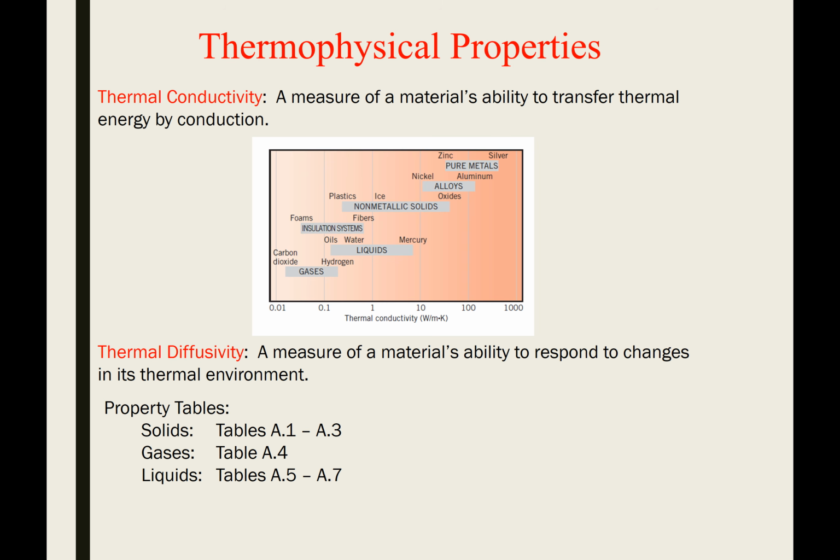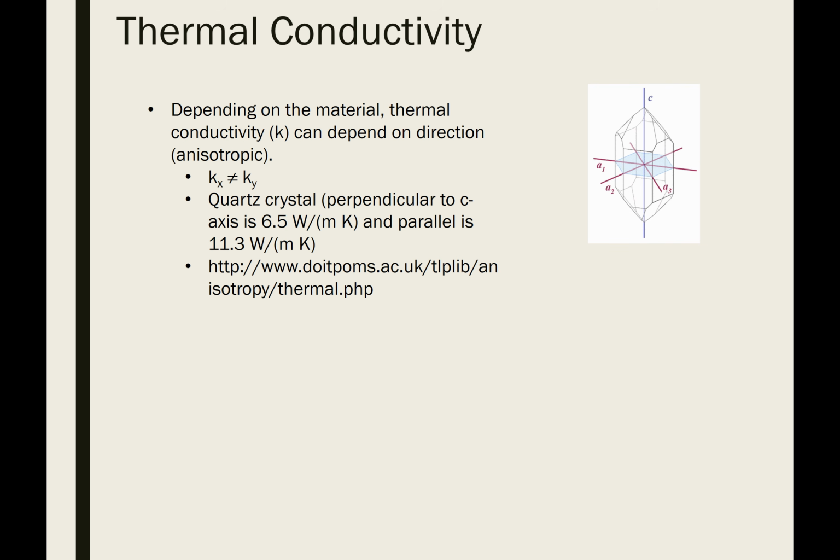So the heat equation, I gave you that simplified form where we were able to pull out K when K is constant, K being the thermal conductivity of our solid or stationary fluid. So K may actually vary, it'll certainly vary depending on the material. It may also be a function of temperature or which direction you're going in.